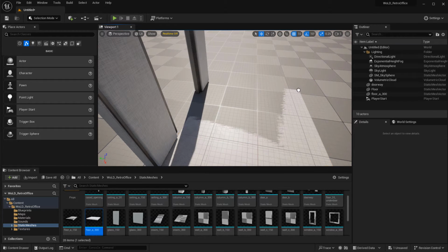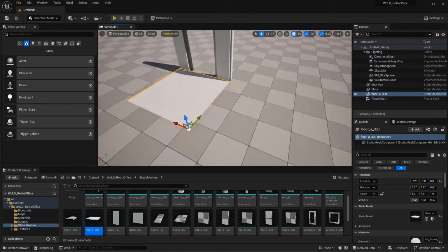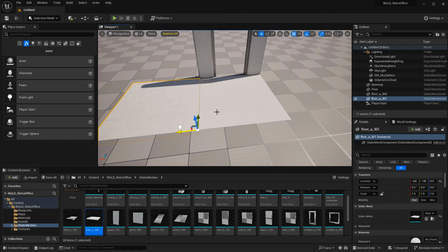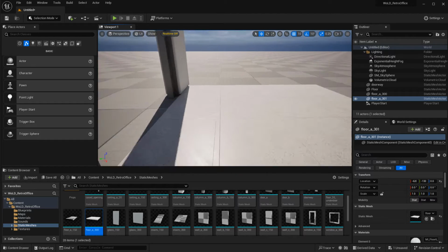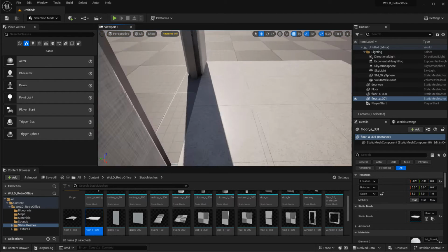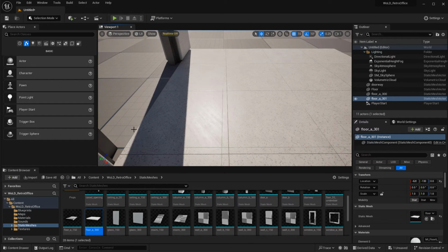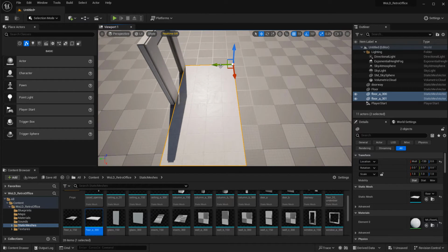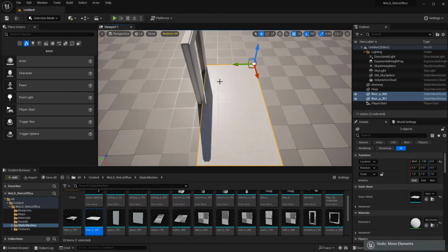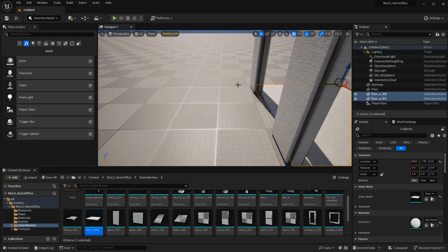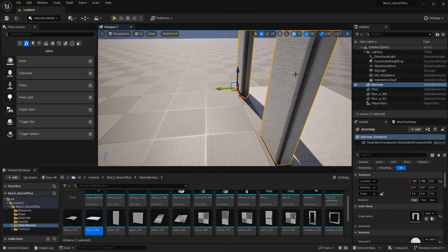So a lot of times when you create an extra room, you may need to have the floor pieces create their own section and not overlap some other pieces of geometry for the walls. Now, when you have a doorway, the doorway doesn't have anything underneath. A workaround would be to take these and just move them underneath as you connect them with another piece of the floor. But a lot of times you may want to just create a section for the room, and there's no connection way. You don't want to connect the floor pieces together underneath another wall or this doorway.